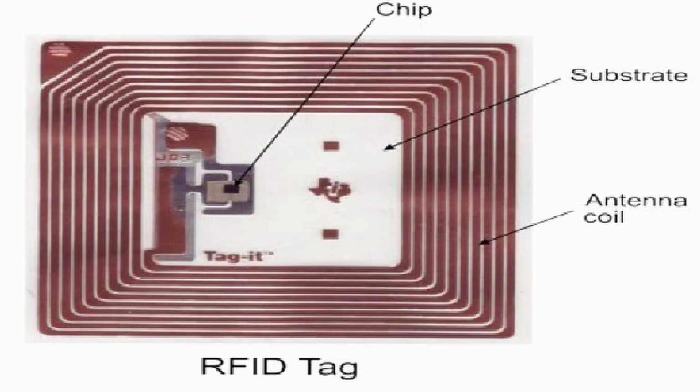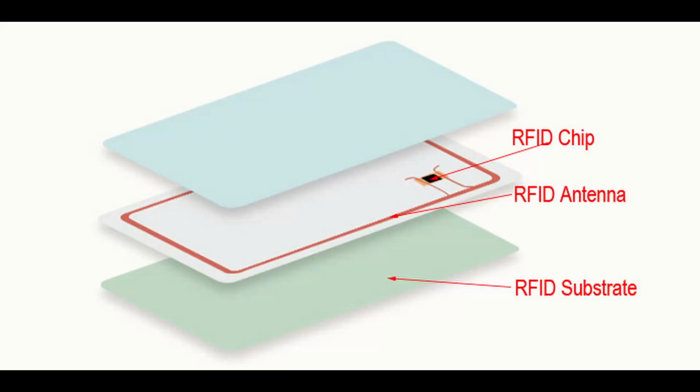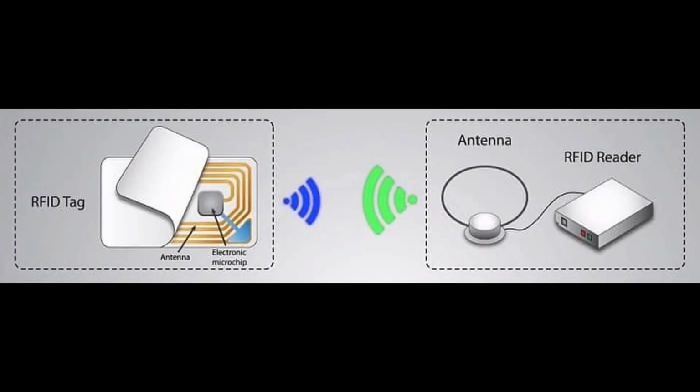So the list of the components in the project will be given up here, but just understand that your card has a chip and can receive and transmit data. Basically, that's it. An RFID card consists of the card itself, a chip, a substrate, and an antenna. So it can both transmit and receive information, but it's more or less a passive component because it doesn't have a battery in it, but it can receive and transmit data. It can respond to the scanner, so the scanning module. But let's get into the main crux of the project. So let's go over the operation sequence of the project.